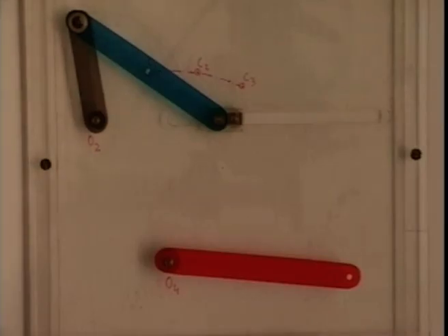We talk of three position synthesis. Obviously, that problem we could have done by the method explained earlier. Here what we are saying is, it is not only a three position synthesis for a coupler curve which is approximately a straight line, we also want to coordinate it with the input movement. That means that as the coupler point goes from first position to second position, the crank must rotate by a specified amount. Similarly, as the coupler point goes from the second to third position, we want the crank to rotate by again a specified amount.